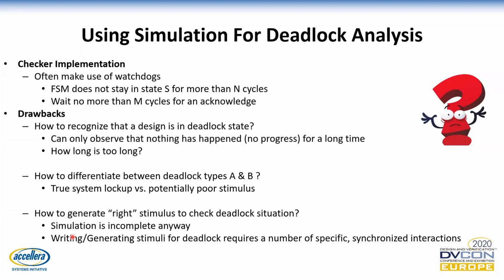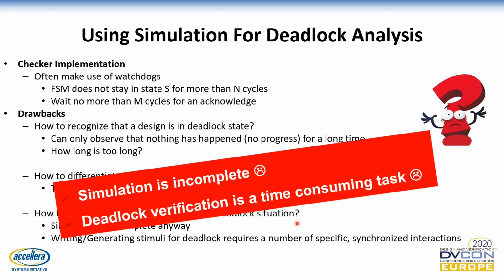The third weakness is a very generic one: writing stimuli is anyway incomplete, or simulation is anyway incomplete. And this is much harder in the situation where we are dealing with deadlocks. Things become very hard and complex. So bottom line, simulation is incomplete and time consuming, and maybe not the right one to use for deadlocks.